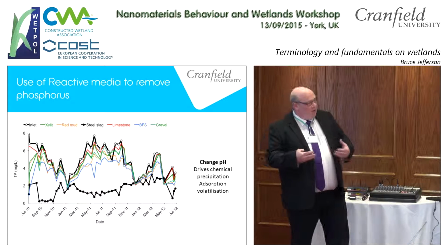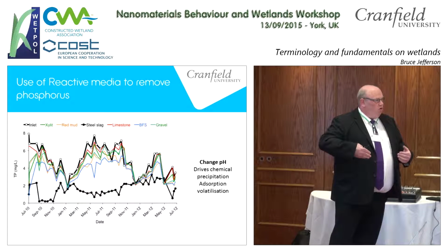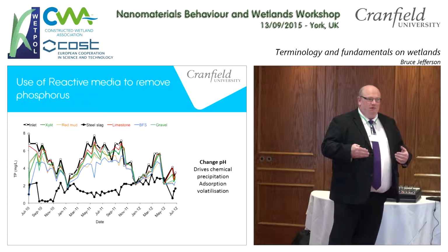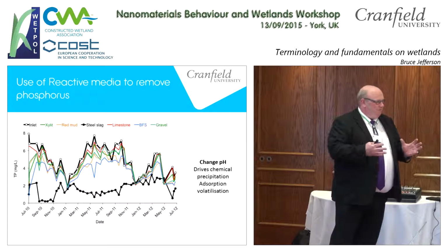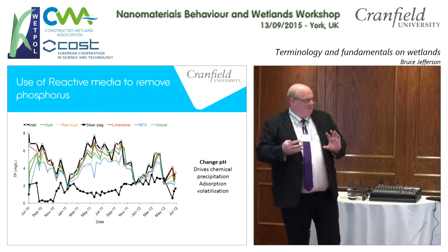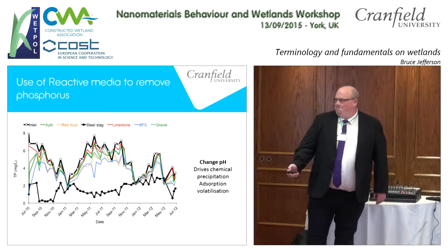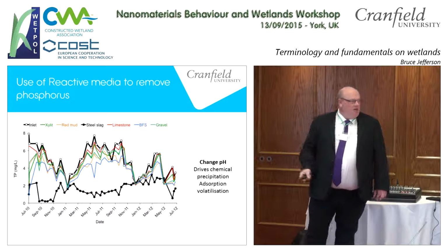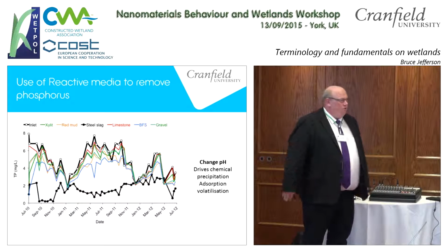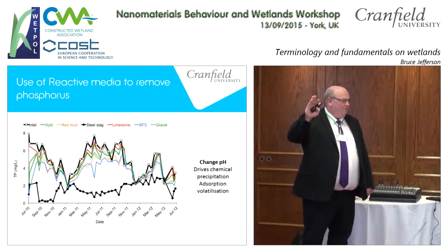But again, it's just showing that as we adapt wetland technology to do new jobs, we've got to be careful that we don't forget that when we're thinking about everything else. Great for phosphorus, but is it doing the rest of the things that we relied upon? And of course, at those sorts of pHs, just through my knowledge of Henry's law, I'm expecting things to just go out into the gas phase.